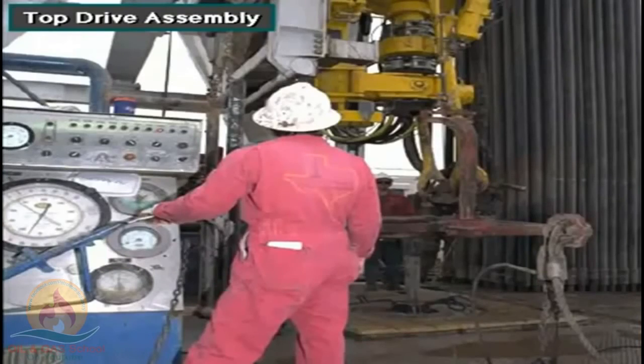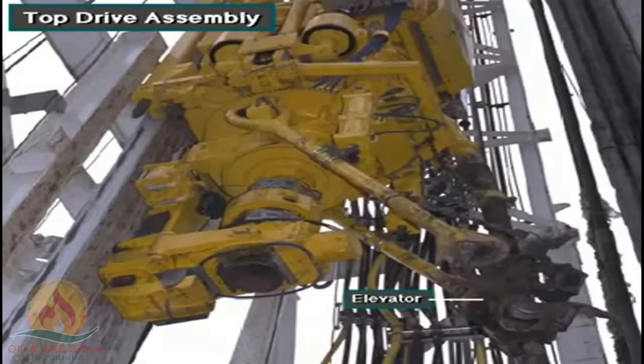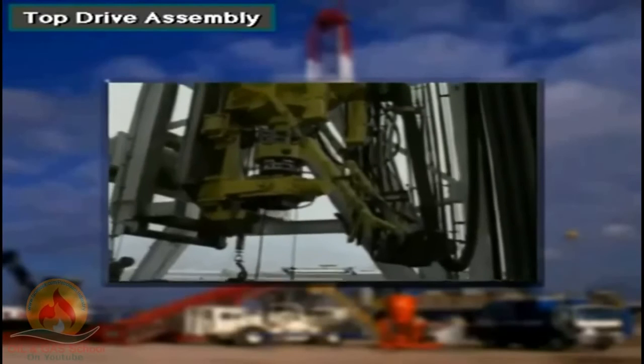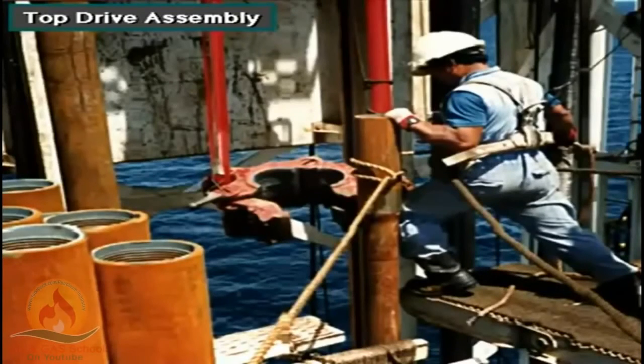The driller controls the top drive's operation from the console. The pipe handler assembly also includes links, an elevator, and an automated link tilt assembly. The driller activates the link tilt assembly to position the links and elevator at the mouse hole for picking up or laying down drill pipe. The link tilt assembly also assists the derrickman in racking stand.